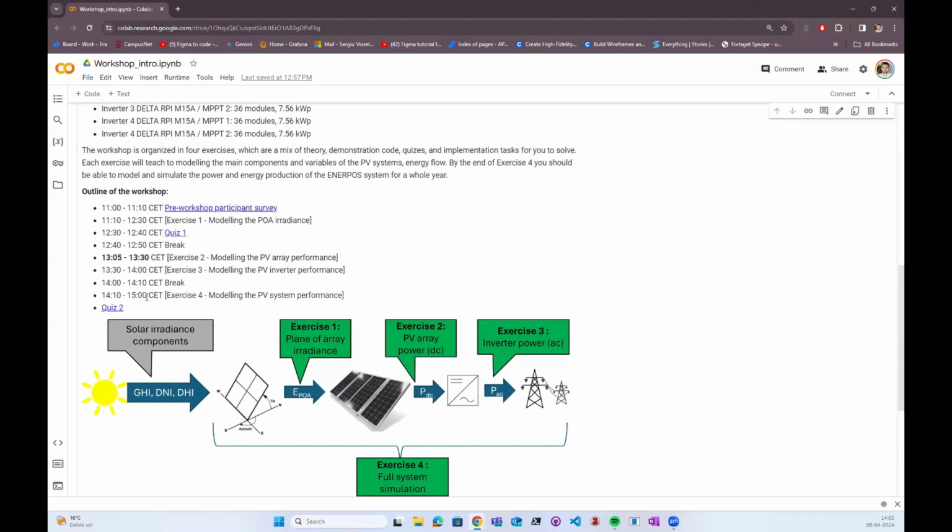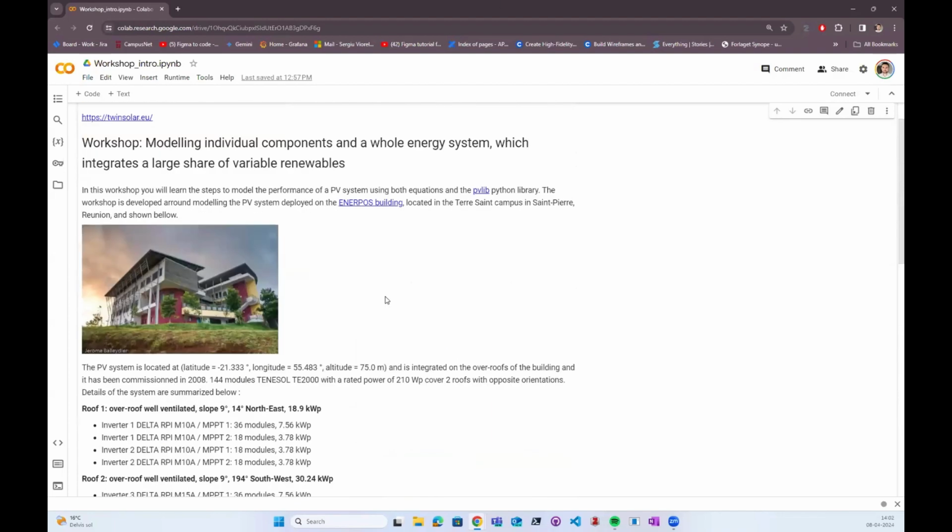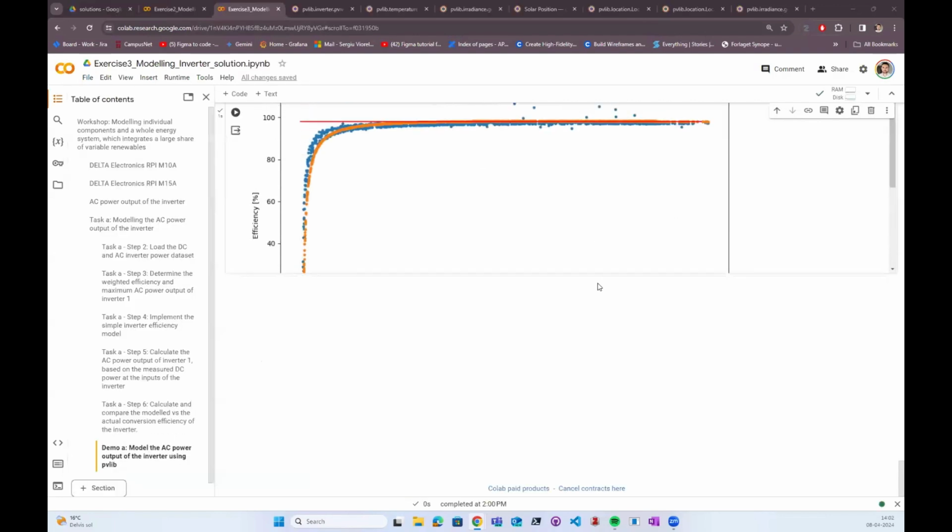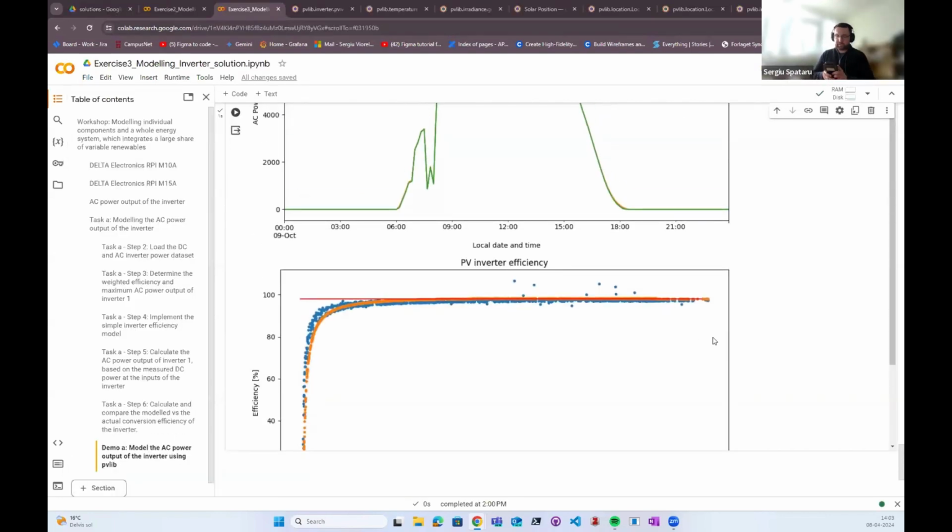Thank you. Sergio, I have just a question before. We can observe in the measured data efficiencies that are above 1. It's very strange for the inverter, no? Yeah, so either this inverter surpasses the laws of thermodynamics, or there is something wrong. It can be that the measurements are not very well synchronized between the input and the output. That sometimes can happen, but it's just a data artifact. It's either the input is not synchronized with the output, or there are some sensor errors, I would say.